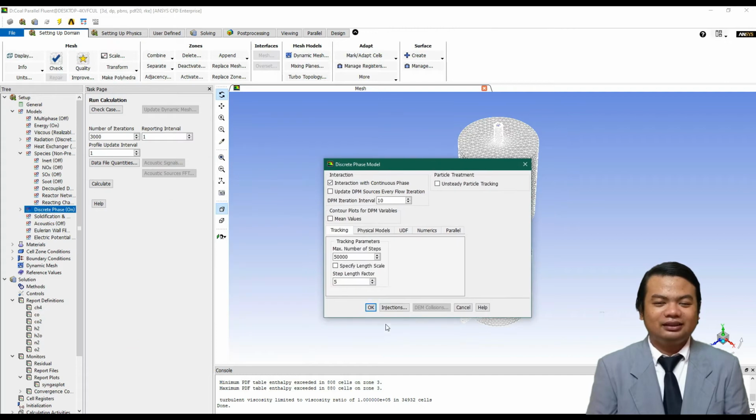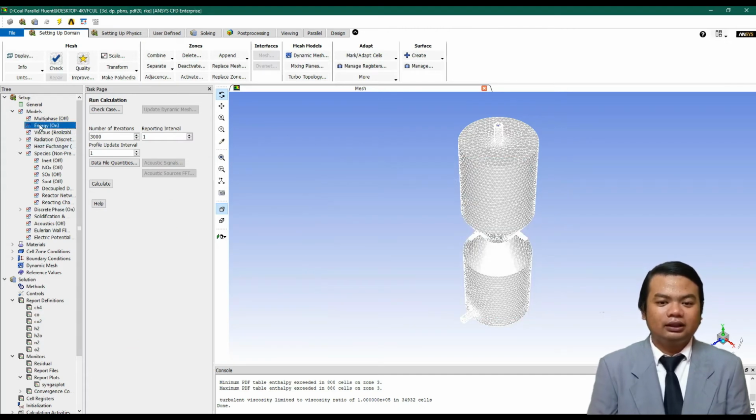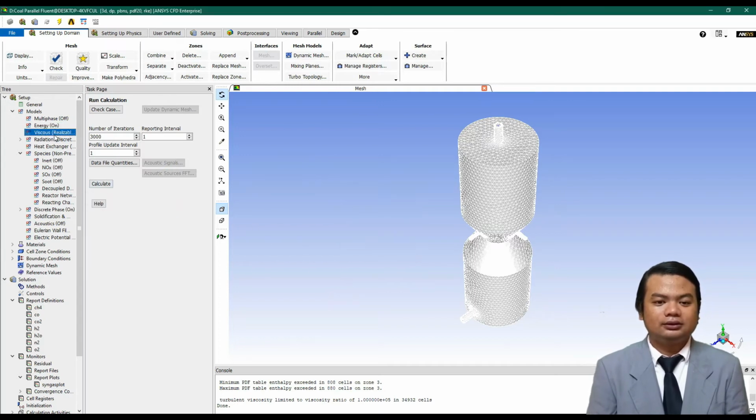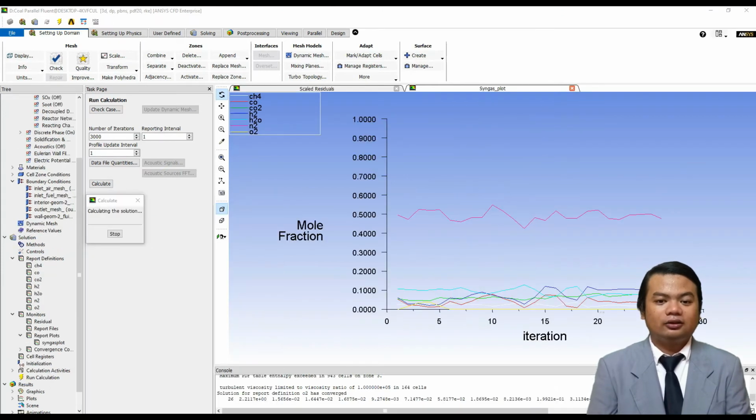During the simulation, the mole fraction for every syngas species produced during the gasification process is predicted by the console for convergence. The convergence criteria was set to 0.0001 in the unit of mole fraction for every syngas species produced during the gasification process.